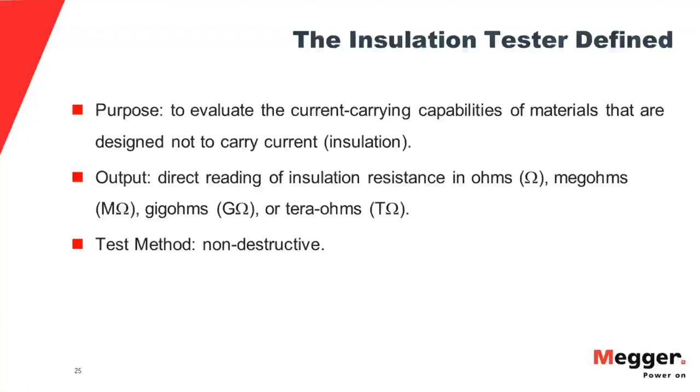And note, we now have direct reading. All the old manipulation is gone. You select a test voltage and it's simply a matter of a selector switch position, and you get all the information you need. We measure up into teraohms. I'll talk about that a little bit later. And the bottom point there, the test method is non-destructive.